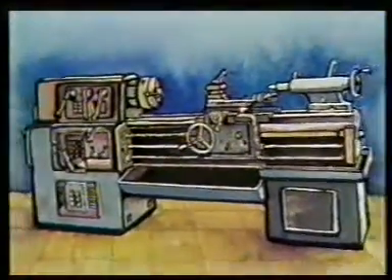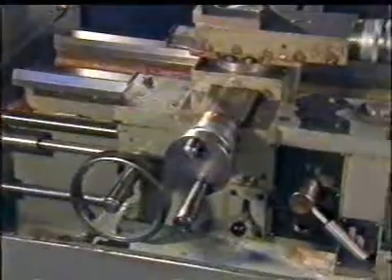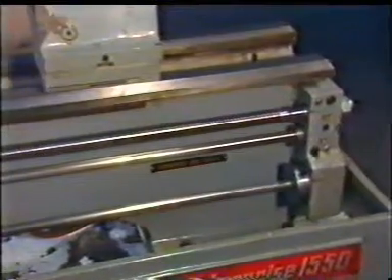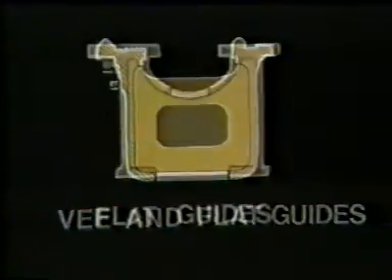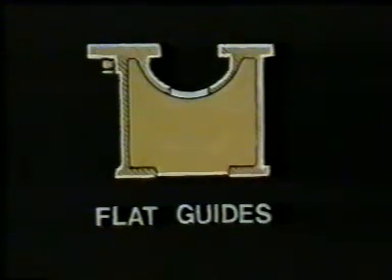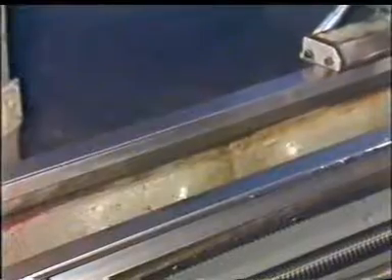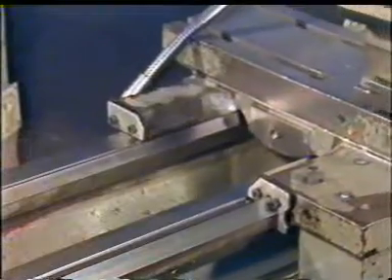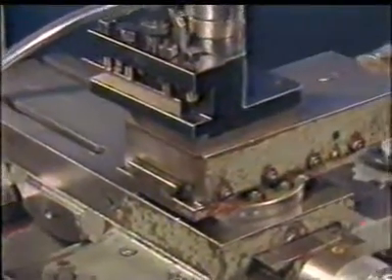A lathe machine comprises of a number of parts. The bed of the lathe forms the body structure supported on legs. It is cast with a box-like cross-section provided with V and flat guides. The guideways are finely finished to have a perfect bearing for the carriage and other accessories to slide freely.